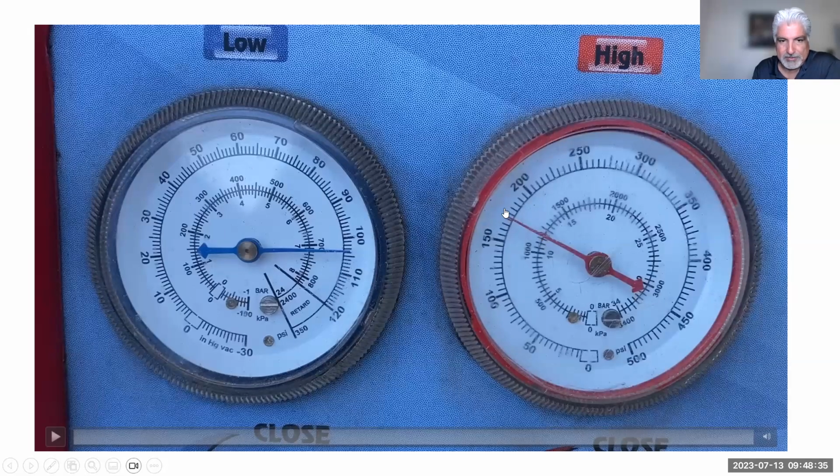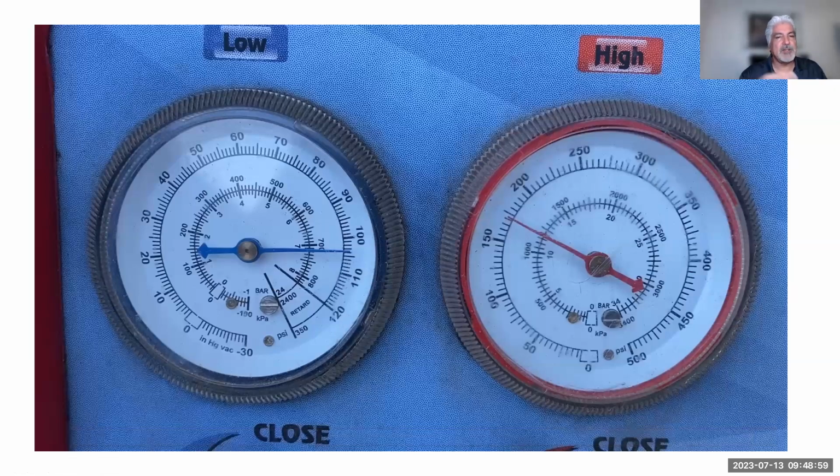And I'm like, wait a minute. I'm reading about what, 150, let's see, the halfway would be 175, so 160. So the pressures are not about the same here, are they? I just realized that. I didn't notice that. What I'm trying to get across is first observe your pressures, because I should have let this system actually bleed off the expansion valve, but I didn't.